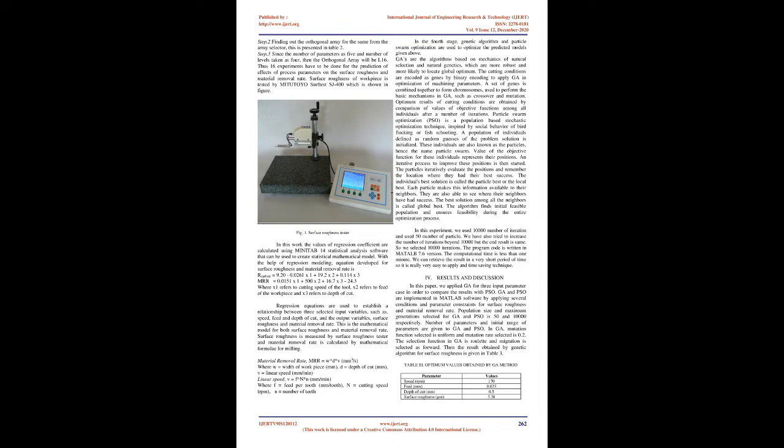The limits of the process variables have to be found out after finding the important process variables that are used for experimentation. The limits are known as the working range of the experimentation. The upper and lower limits of the process variables have to be found out within which the experiment has to take place. The selection of the limits of the process variables is followed by choosing the number of levels within the limits of variables. Usually the upper limits and the number of levels of the process variables are chosen by conducting trial runs by changing one of the process variables and keeping the rest constant.